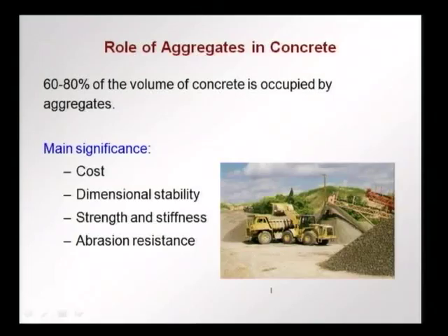Cement, as it hydrates, shrinks, and due to temperature and so on, there could be changes in the volume of the hydrated cement paste. So, if we have a very high volume of hydrated cement paste, there could be major volume changes in the concrete itself. The presence of the aggregates mitigates this and reduces the volume changes that could occur in the concrete.